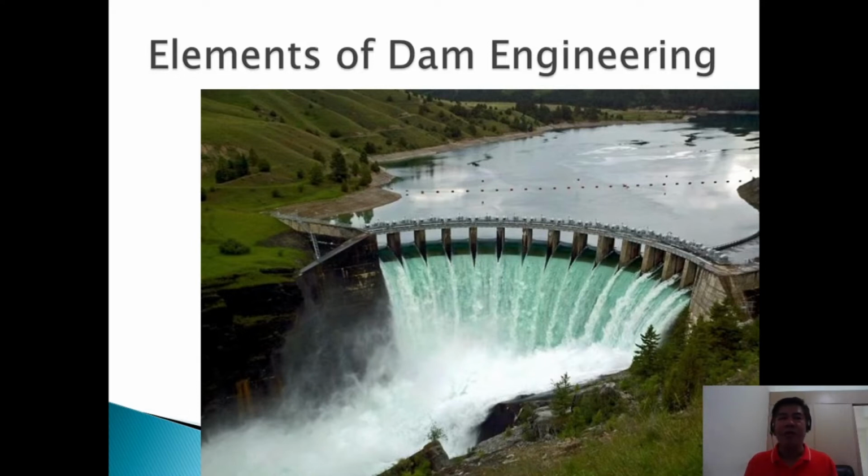For example, we studied dams before in terms of overturning and resisting moments and forces. Then you compute the factor of safety, then the resultant in the different cases: is there water on the upstream, is there water on the downstream, is there an uplift pressure, and so on.